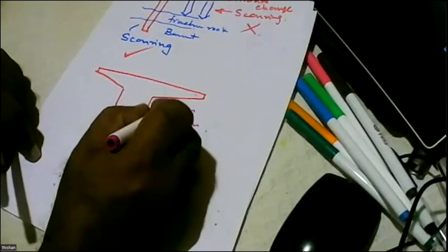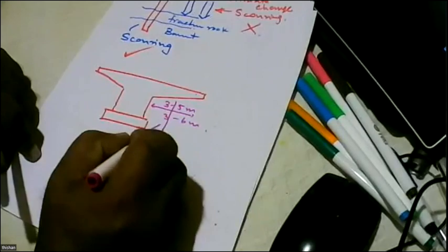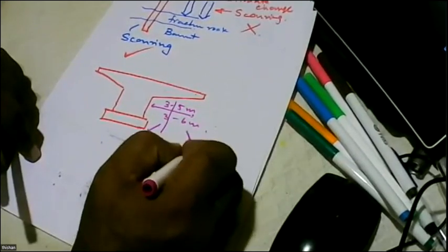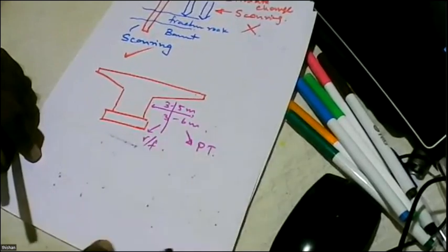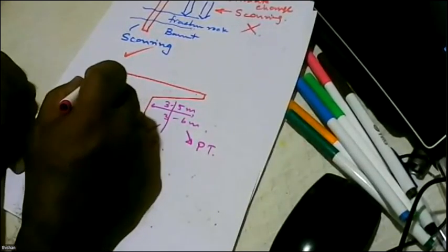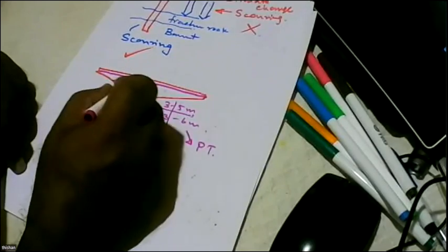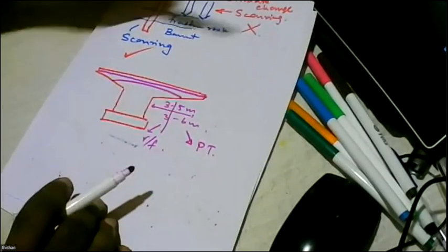When you have large cantilevers, in this range reinforced concrete might work. But when you are going for this range, you have to go for pre-stressed concrete. And you might have to do the pre-stressing in 2 stages, and you might ask why.